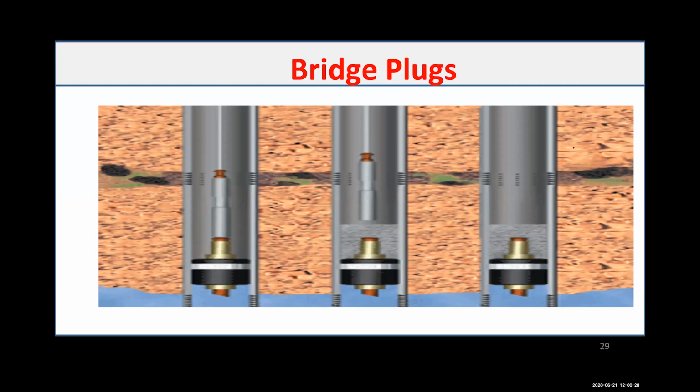Bridge plug is the same concept: you usually put the plug, treat the zone, and then remove it, put another plug, treat the zone, and remove it, step by step.